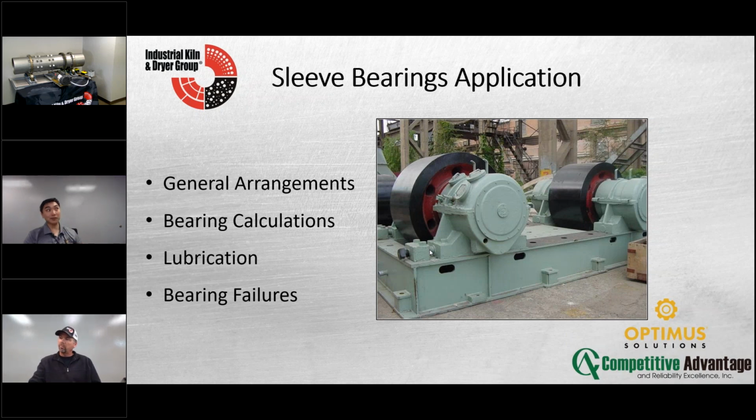We did have a customer that had 3 units, and they did fail 3 thrust rollers all within a month. Wow. And that one was a pain for them in terms of getting a spare. And as far as the spares go, I would have a complete assembly. That's your support roller shaft and your 2 bearings, and actually have it assembled and ready to go. Yeah. So on top of that, having assembled bearings and everything done, but in terms of the trunnions and bearings, have a set, 1 trunnion, 2 bearings for each component or each dryer.